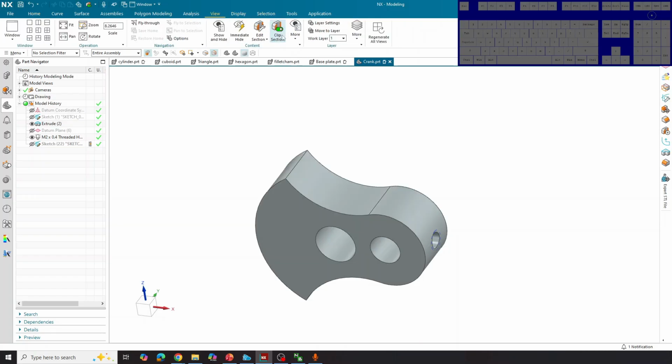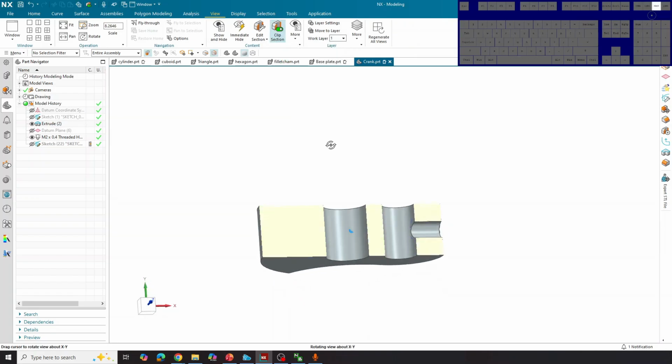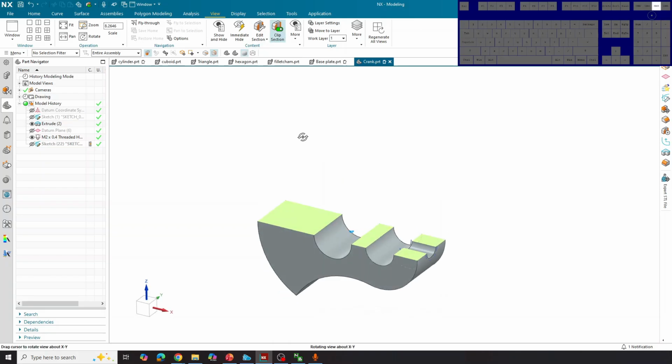So you see over here, inside of the circle, because no material is cut, the texture is different. But where the material has been cut or sliced through, we make it obvious that it has been cut by either using hatching lines, or in the 3D model's case, using a green color.